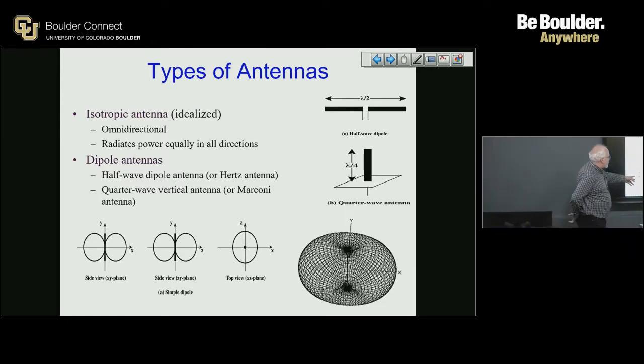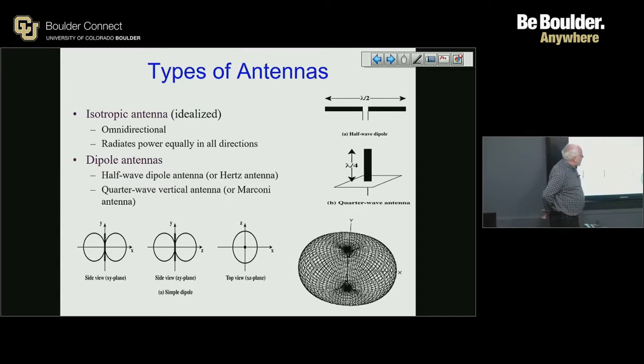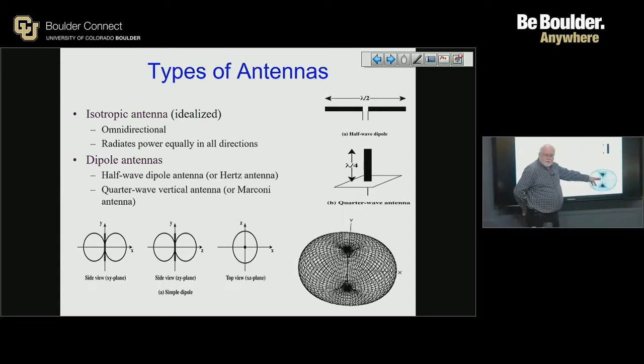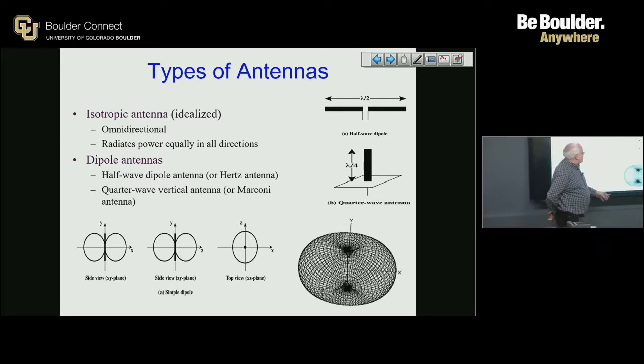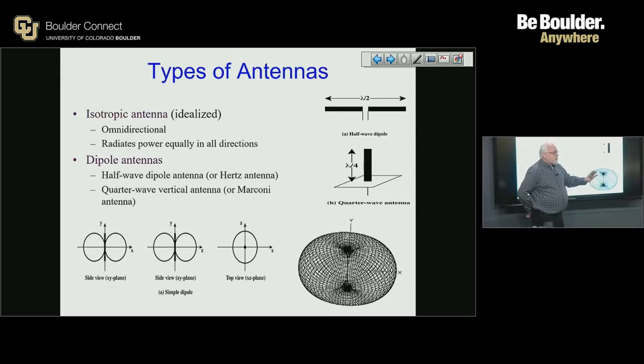These have been known for years and years, so the antenna patterns are very well defined. You can see this donut shape. These are very common in Wi-Fi access points, because typically in an access point installation, you're going to try to cover a room or a part of a floor. You're not generally trying to go downstairs. Access points are designed with these kinds of antennas so that they cover things basically in 2 dimensions, and they're not trying to go up or down with the pattern.